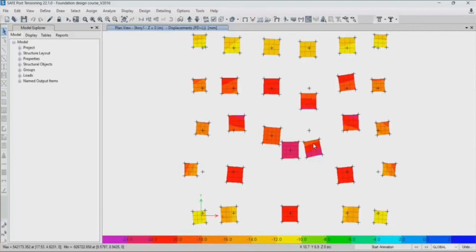So let's say this footing and this footing, after increasing the area of this heavily loaded column, the settlement is still way higher compared to the settlement of this other footing, which will cause differential settlement. So the second way is you can introduce a tie beam that will tie this footing to this other footing.